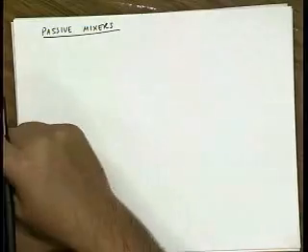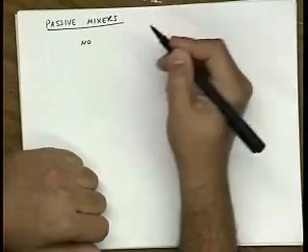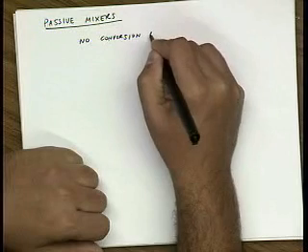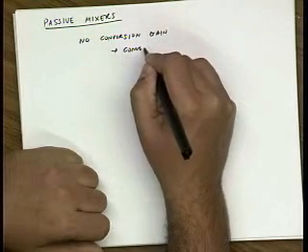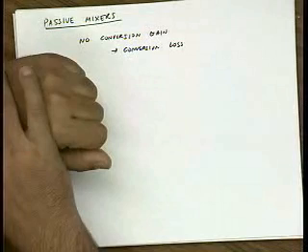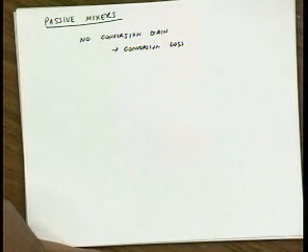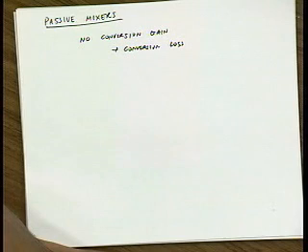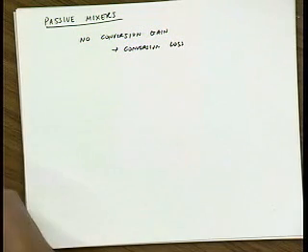And the distinction between passive mixers and active mixers is there's no conversion gain. Or the conversion gain is actually negative, so there's conversion loss. And typical loss numbers might be anywhere from a few dB to about 10 dB. So you might say, well, that's terrible. That's a lot of loss. How do you deal with that? Well, as we'll see, these passive mixers tend to be very linear and sometimes also very low power. So even though they have loss, they're very linear. And so you could put lots of gain in front of them because they're linear, or likewise put gain after them. So they're actually quite useful and used quite often.